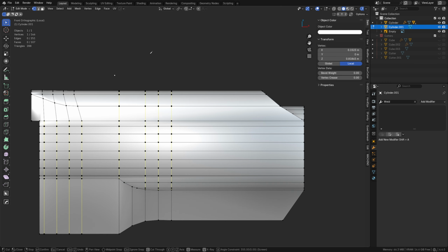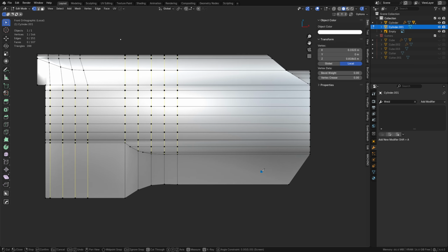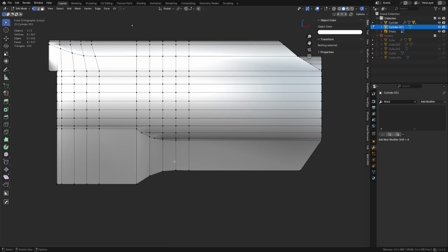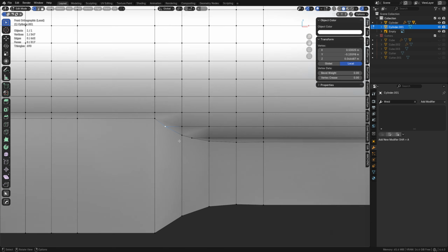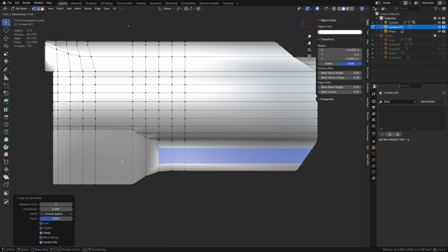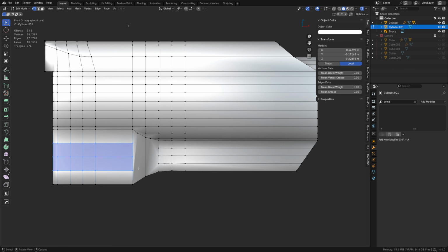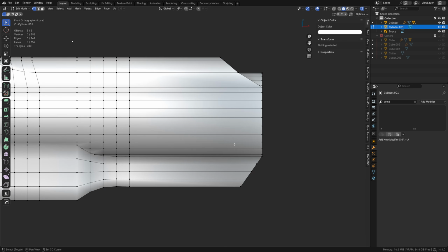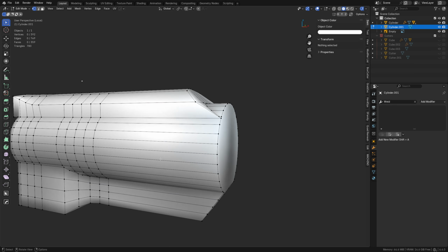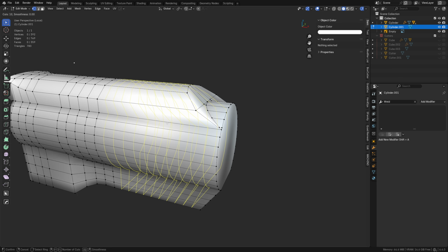And in our case here, I think we'll be okay. And I'm going with the bottom ones for now, because I think I'm going to shift these ones around. And that takes practice to understand when you might do things like that or not, but you might do it at some point, so it's worth just seeing what's going on here. So we've isolated this whole area for the most part. Maybe we can add a couple loop cuts here, maybe three up here. Eventually we can join these with J, just like the two verts. It starts to become a lot easier to work with a lot faster. You do these cuts that are needed. And then later on, when you have these big sections like this, you can just loop cut through there. Don't think too much about it later on.